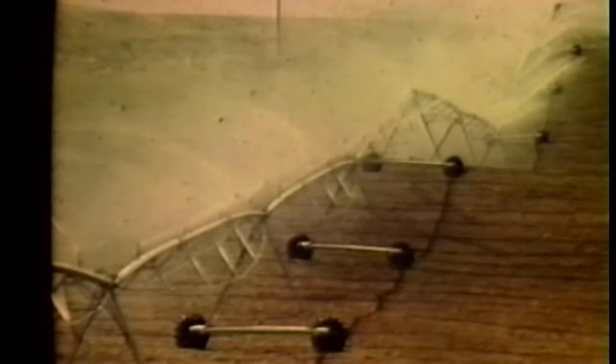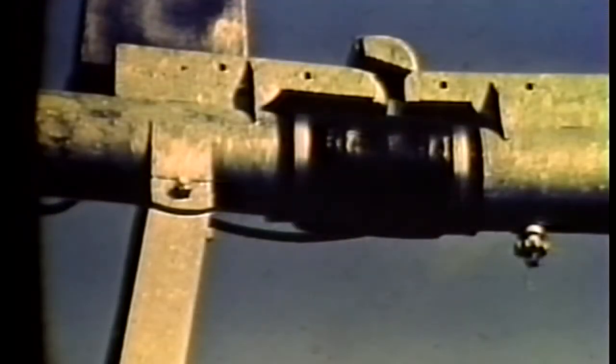Rough land, such as that with irregular slopes, streams, and ditches, is a problem with most types of systems. Hand-moved and permanent systems can be designed to fit such conditions without too much difficulty. Self-propelled systems can be used on rolling land if a reasonably smooth path is available for the wheels to track, such as bridges over ditches and gullies, steps over piping and terraces, and flexible coupling in the lateral.